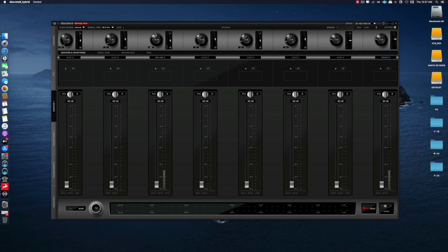You can see the signals are coming. I am selecting preamp 3 in the selection menu. Click on the Headphones 1 tab. I am using the Audio-Technica ATH-M50X headphones, setting the output level as -12 dB. Discrete 8 headphone output supports impedance from 16 ohms to 600 ohms.